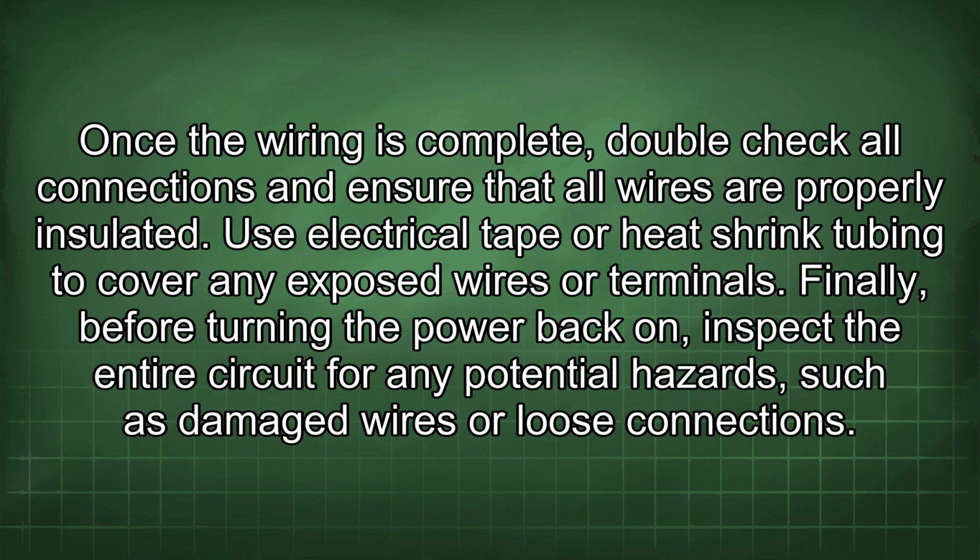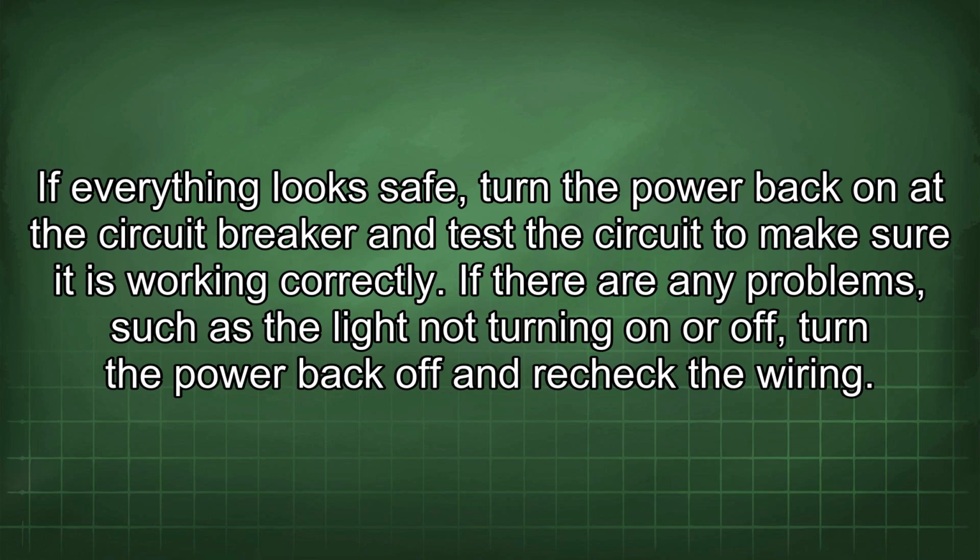Finally, before turning the power back on, inspect the entire circuit for any potential hazards, such as damaged wires or loose connections. If everything looks safe, turn the power back on at the circuit breaker and test the circuit to make sure it is working correctly.